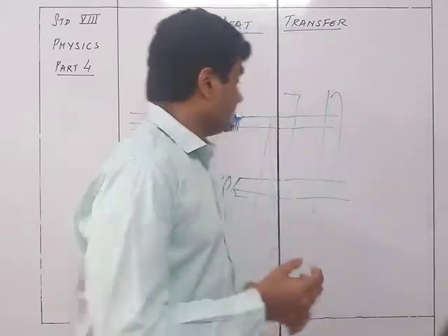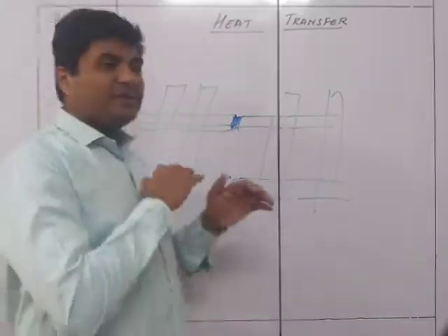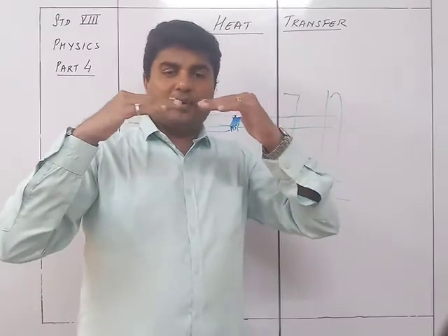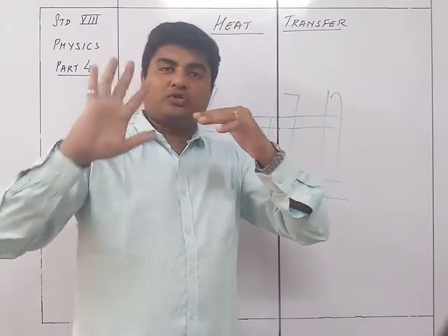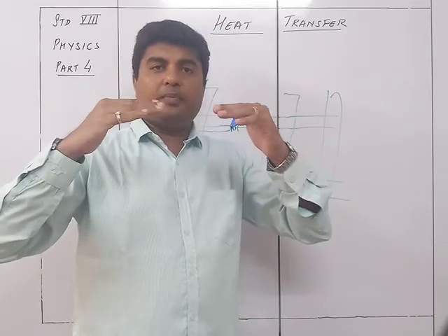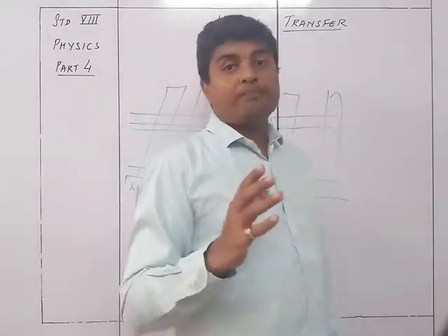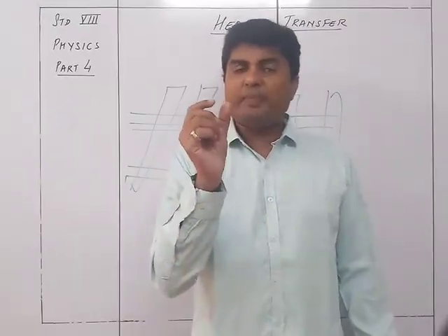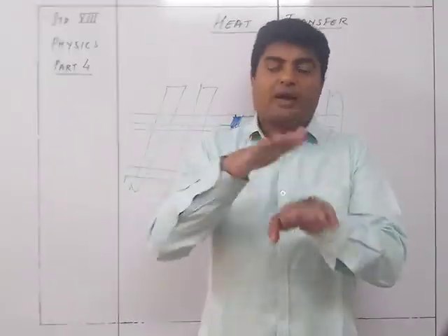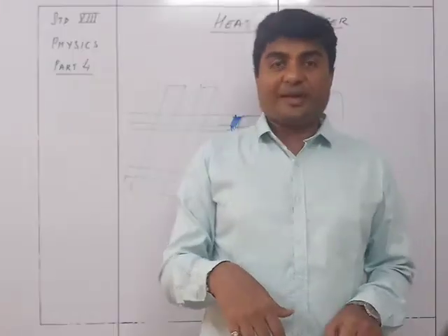So this gap over here, as soon as the train passes, the expansion is going to take place and it is going to come very close to each other. When the train has passed and it is cooled down, again it will be back to normal. So in this way, the train will be able to go smoothly because the gap will not be so big that it can have a kind of a hindrance to the train for its travel.